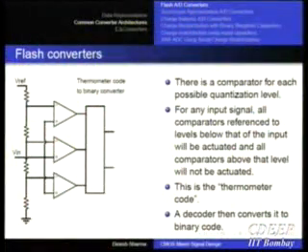So again, just so that you don't fall asleep, what would be the problem in parallel D to A? Can that be made an arbitrary number of bits? Why is there no power dissipation? Yeah, but essentially overall power is V by 2R. If everybody is on, so the current is V by R, V by 2R, V by 4R. So overall current cannot exceed 2V by R. Okay, so you choose your R properly. That is not a fundamental problem.